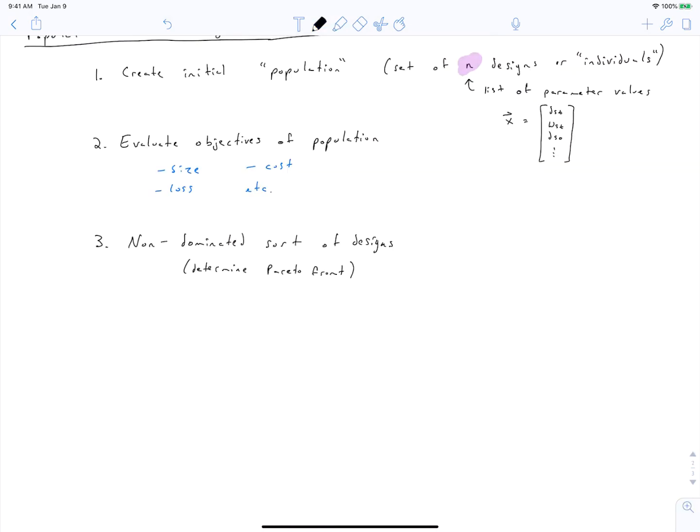Next, your optimization algorithm is going to sort the designs. And in a multi-objective optimization, where you are considering Pareto optimality, you do what's called a non-dominated sort. So you rank the designs, and your first rank is going to be a bunch of designs that are tied, that are Pareto optimal, that do not dominate any other designs. And then your lower ranks, further on down your list, are going to be designs that are dominated by preceding designs. So your first several designs are going to all be on your Pareto front that you've evaluated so far.